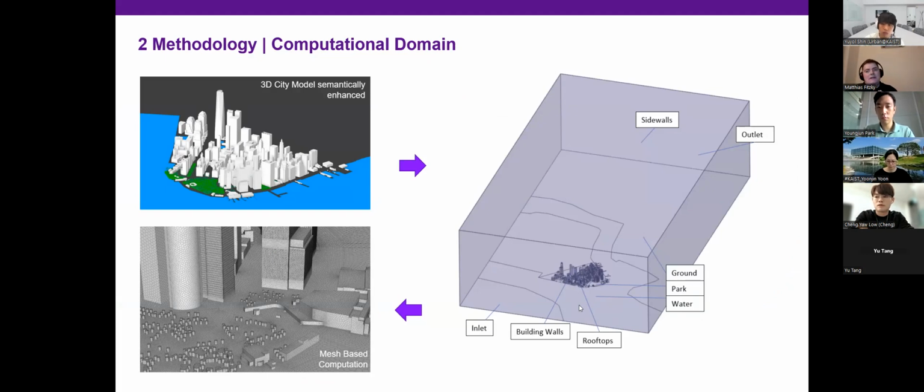And that is a condition applied at the inlet. That profile has its shape based on the surrounding features, which are not directly modeled. The way it's implemented is you have a so-called power law, and this power law has a certain constant, which represents a certain roughness of the features before we enter this explicitly modeled area, which we see on screen.